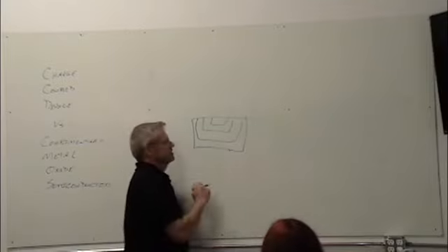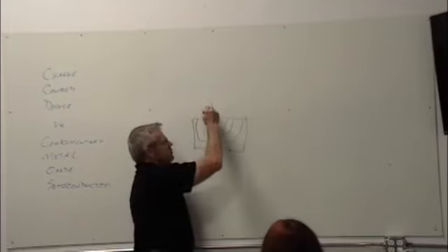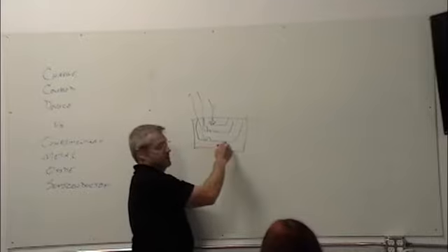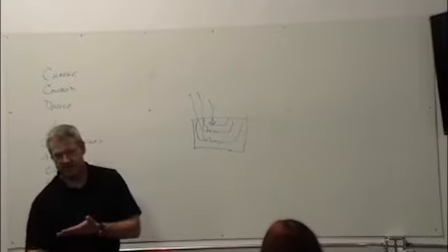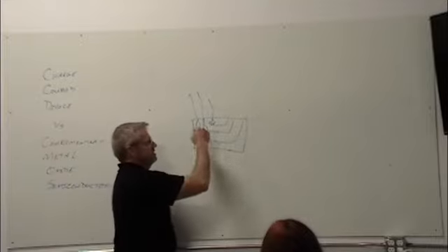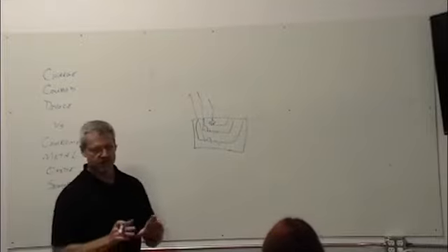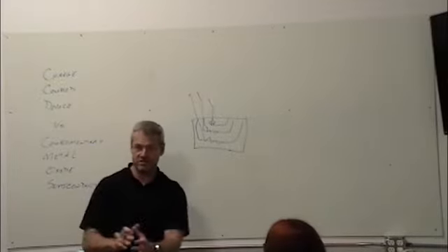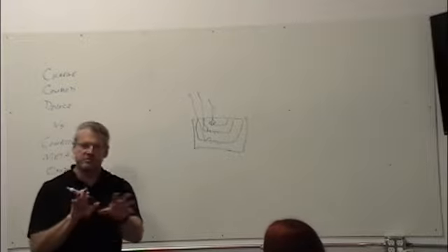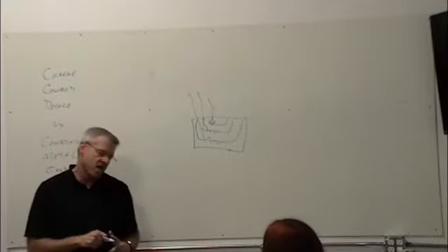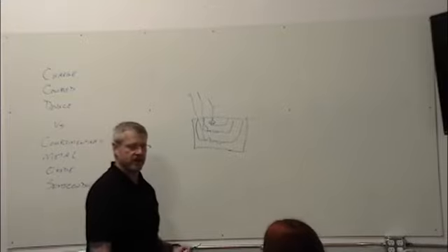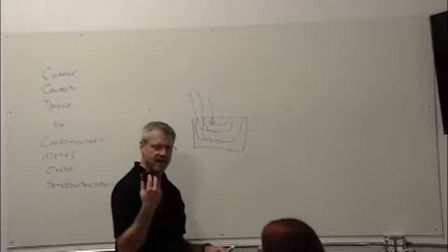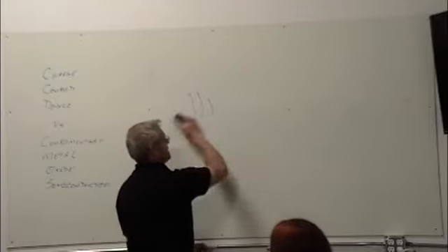And I talked about this just a little bit, I think, at the beginning. Blue absorbs here, green absorbs here, red primarily absorbs down deep. Red makes it further in before it absorbs. So they did this, and they did a bunch of calibration tricks, and they were able to put a red, green, blue in the same pixel. And that was a big thing. We can give you a whole lot more resolution, and you don't have alignment problems between them because they're offset from each other. But I don't think it went anywhere. It was a couple of years, but I think it died. I think it wasn't worth the hassle.